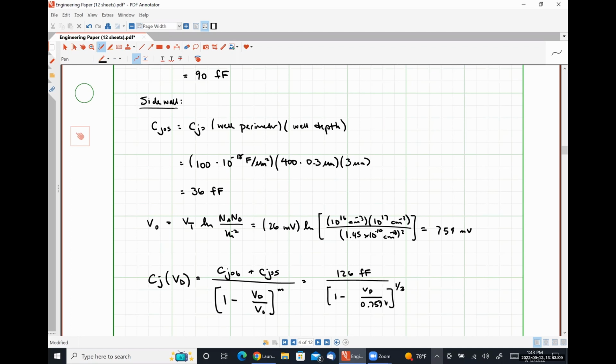So what do you think happens when we have a section of material that exhibits both a resistance and a capacitance? It introduces delay into our signal because it forms an RC ladder network. So we are going to talk about what kind of delays arise when using N-well as a resistor material when it's got a voltage applied to it. And that'll finish up our discussion of N-well type things.